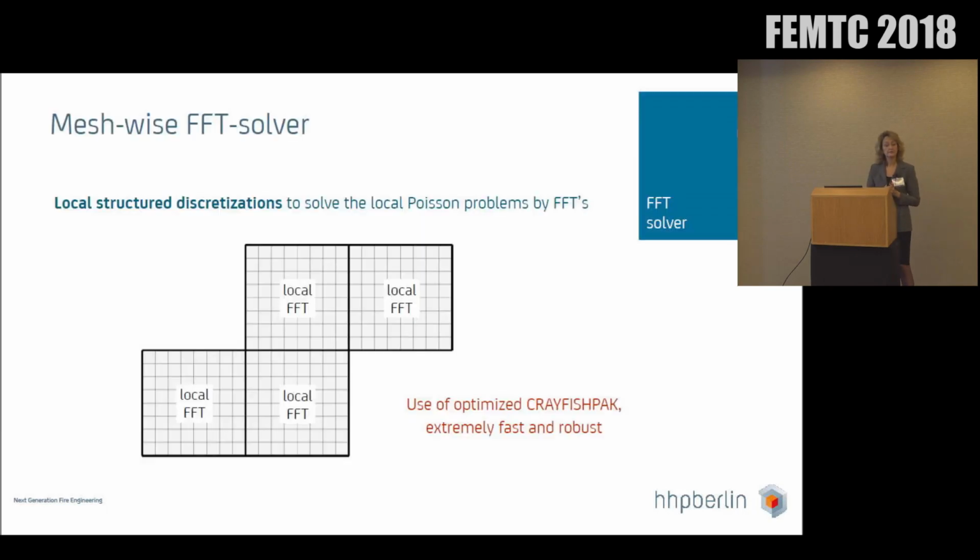Now let's have a look at the current FFT solver. The FFT solver is based on local structured discretizations. So in each mesh, a local Poisson problem is solved by a highly optimized local FFT method, which is taken from the optimized package CRAYFISHPAK. And this one has proven to be extremely fast and robust over the last years. In fact, I don't know any Poisson solver which is faster.